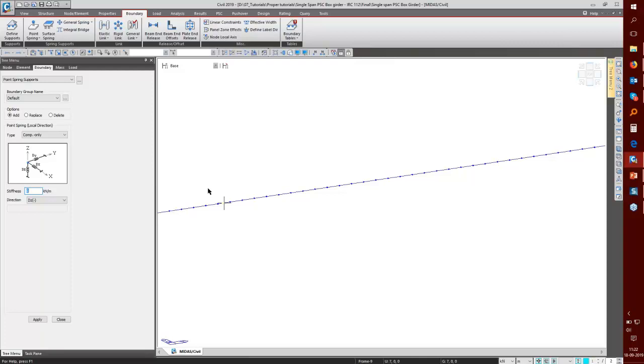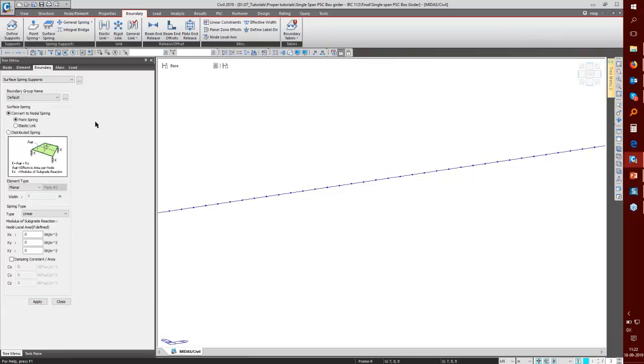So when we see the shear force variation at the bottom of our box culvert, or the bending moment variation, it wouldn't be like we expected. Rather, it would be a zigzag behavior because the spring reactions are as per point loads, but we want a UDL kind of distribution. So during that time, we use surface springs, right?